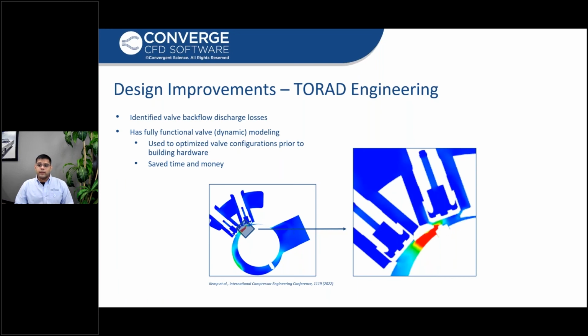So based on this CFD model, TORAD Engineering, whom we were working with for this project, was able to identify that there were significant valve backflow discharge losses, and they were able to use our valve modeling feature to optimize the valve design.